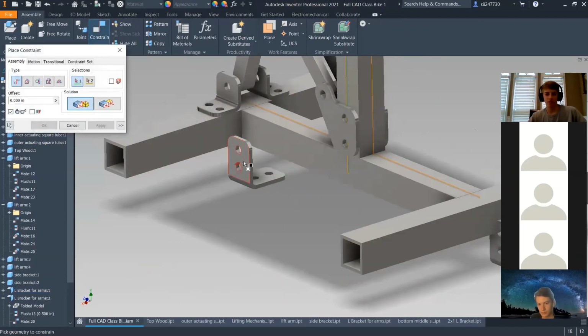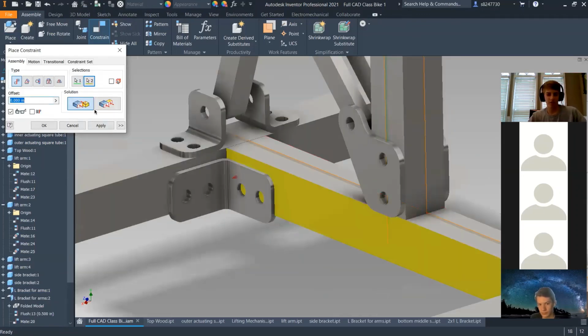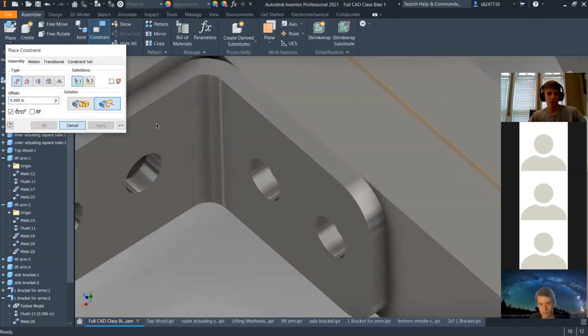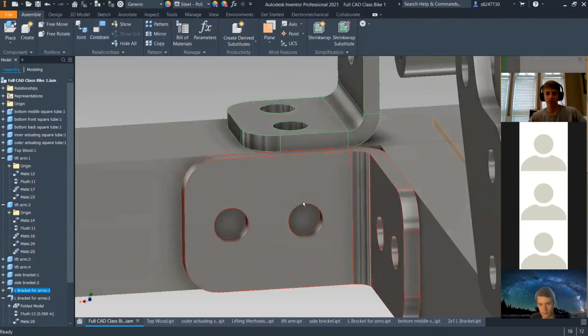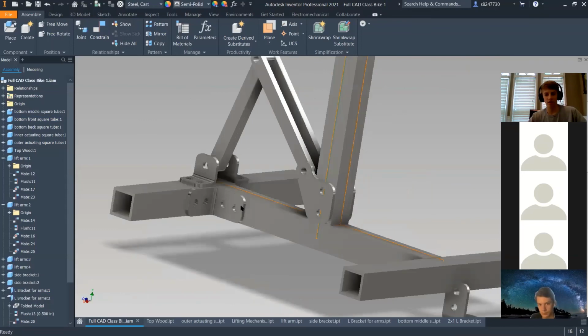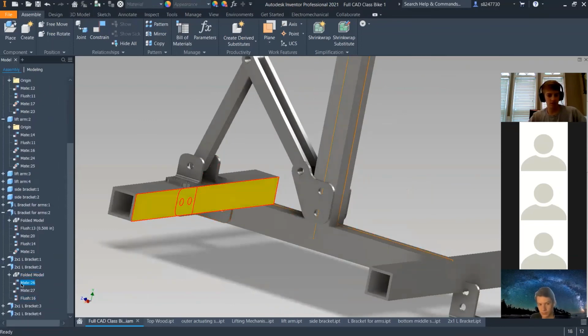So that was where I did. We're not actually putting this type of L bracket right here because it won't work. So I'll just show you why we can't do it. If we have bolts going down through here, they'll hit this bolt. So what we have to do is copy this L bracket and take out this hole so that we only have one hole there.